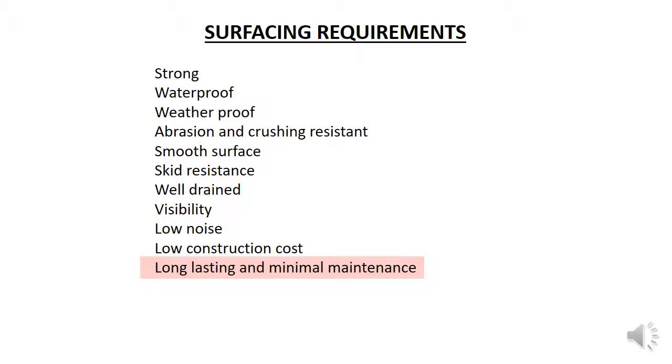Cracks or other defects in the surface can result in water draining into the base course layer, so reducing its strength and potentially resulting in other damage. The loss of surfacing also removes some protection to the base course surface, so increasing the risk of the surface unravelling. It also needs to be remembered that the cost of replacing a road surface also includes the costs related to reinstating road markings and other features on the road.